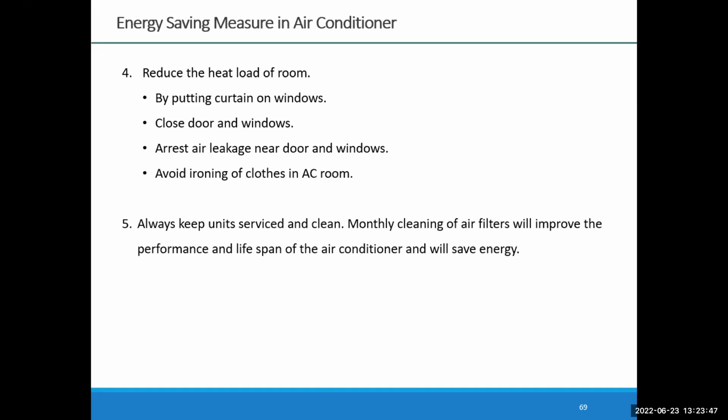Always keep units serviced and clean. That means, as per the vendor specification or original equipment specification, we need to clean the outdoor units, the radiator, every 6 months. If at all any dust accumulation is there, we need to clean.